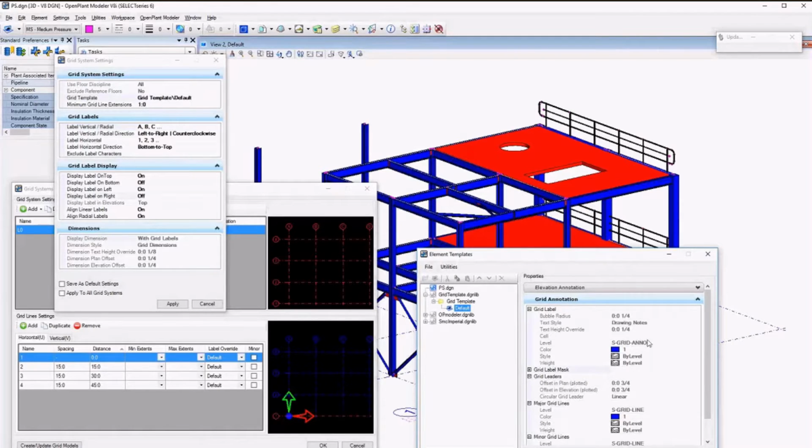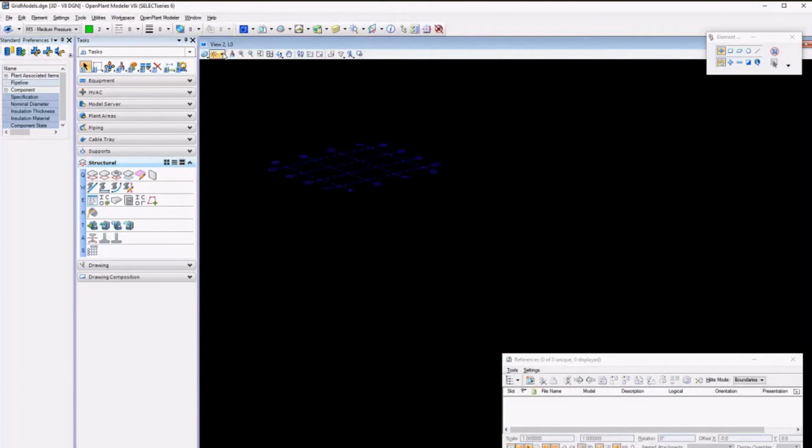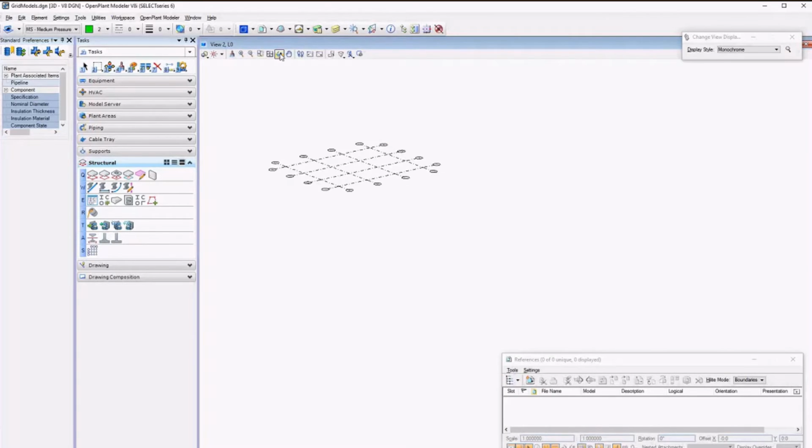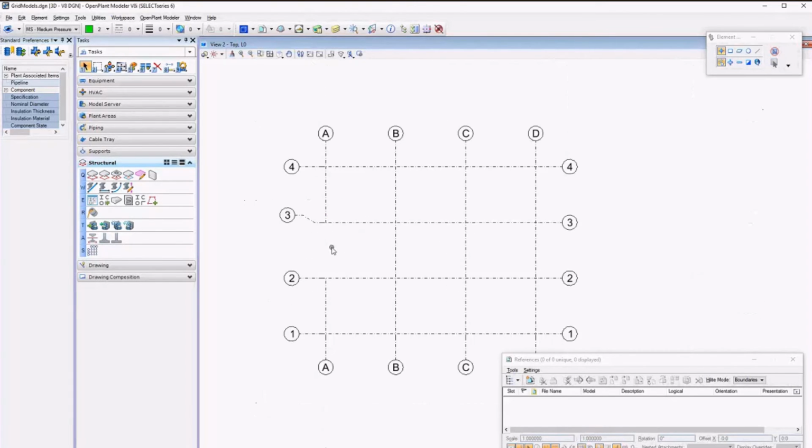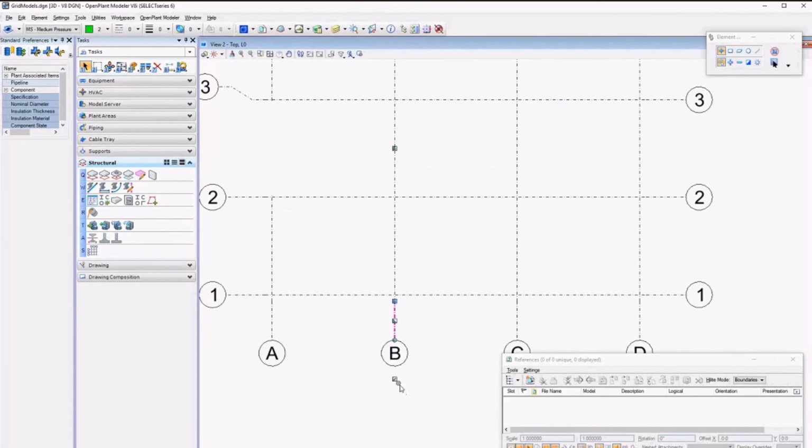If grid model is opened up individually, we can even modify the grid representations using the handles and introduce dog legs and create any white space or hide labels. Basic MicroStation functions can be used to override the definition. These changes are only in the representation, and the actual definition file stays the same so that you can always revert back if required.